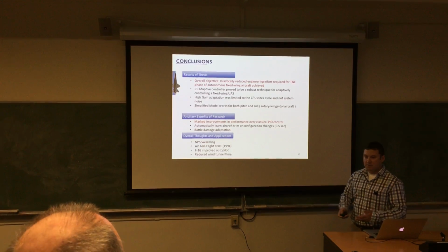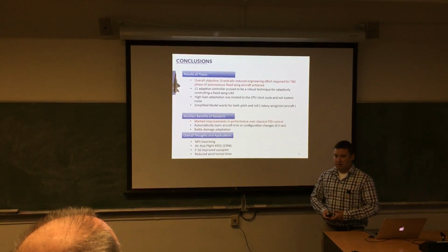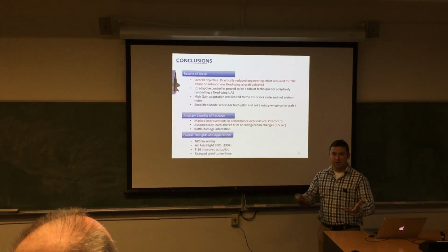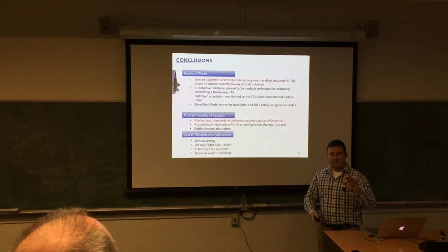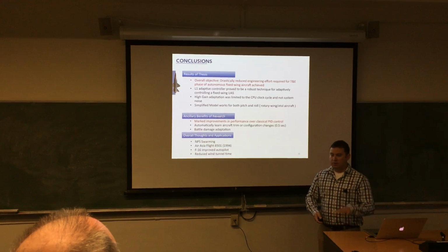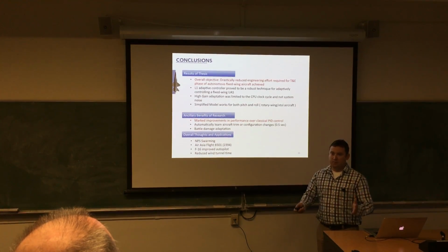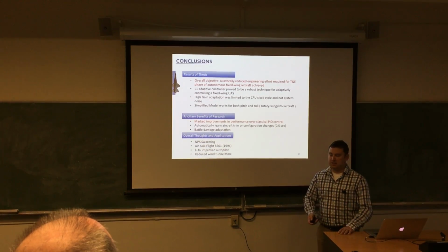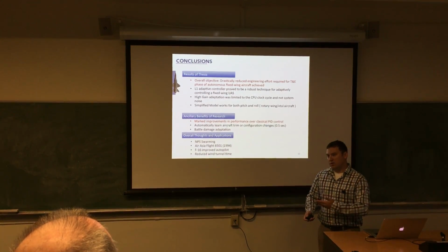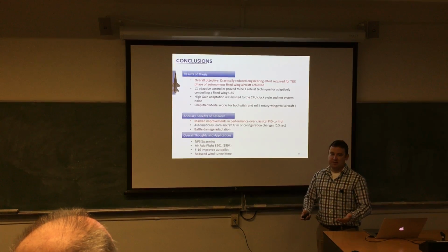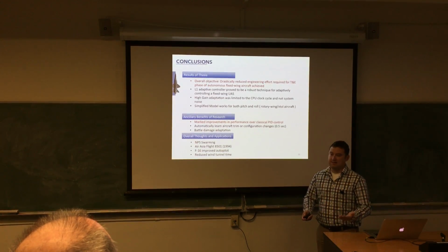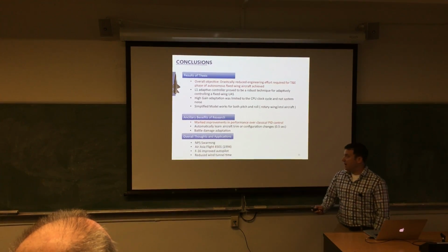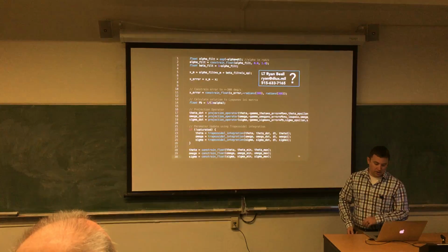Some other things, like F-16 improvement to autopilot. The F-16 autopilot struggles in asymmetric loading. So if you fire a missile off of one side and you have a missile on the other side, at high angles of attack, the pitch flight controller rapidly departs controlled flight. It's a known thing. They tell the pilots, hey, just don't exceed these limits. But with a control like this, you don't care about these asymmetric cases, because the controllers adapt in real time anyways. So with that, I'll leave you with the 30 lines of code.